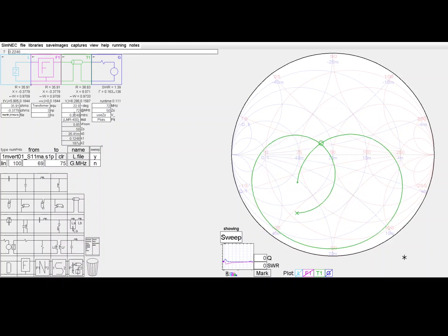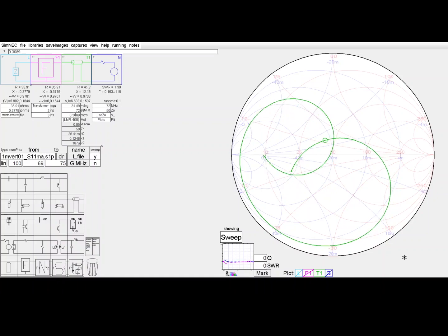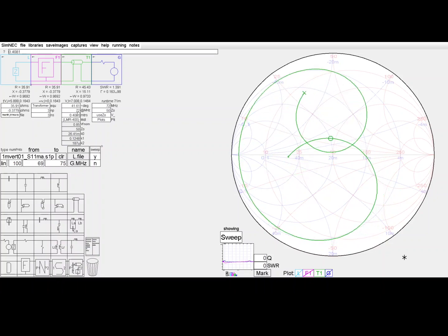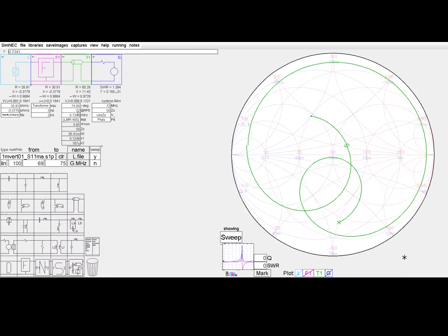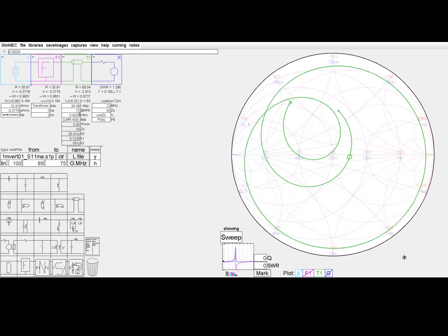And it might not be terribly obvious where it started. So if I go far enough, you get some quite different patterns. This is all caused by rotation. In this case, the rotation is just over 90 degrees at 70 megs, but at the top end of this sweep, it's more like 270 plus degrees, 300 odd degrees. Let's return this to 0.